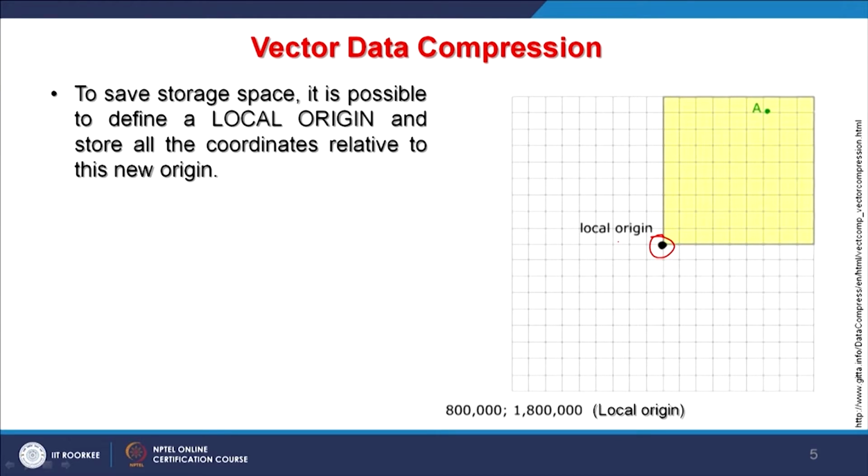And in that way, this is basically going back to a geometric system, but only for a small area. This is what civil engineers or surveyors sometimes do. Instead of using eastings and northings in the case of UTM projection, or latitude and longitude in degrees, minutes, seconds, they have their own coordinate system, because the area may be 1 square kilometer or maybe 5 square kilometers.